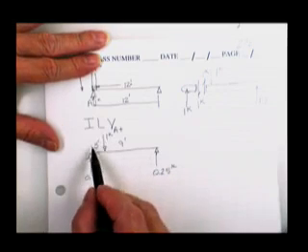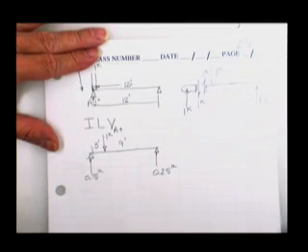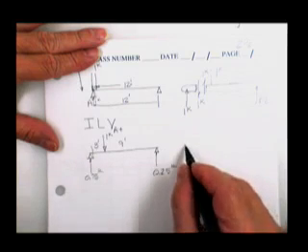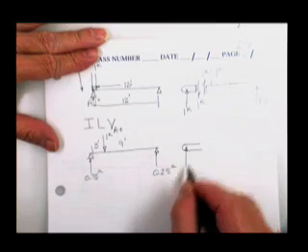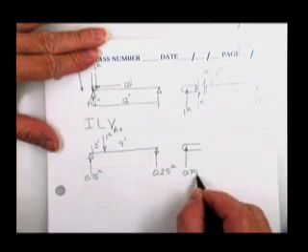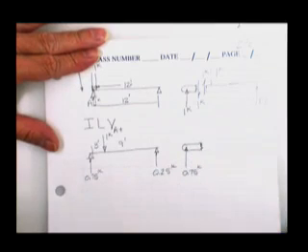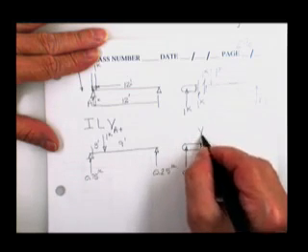And I am going to cut the beam very close to the reaction because that's where you've been asked for the influence. You've been asked for the influence inside the beam in shear, slightly to the right of point A. Here's the free body. Here's the 0.75 reaction. Here's where you cut it. And here is the resulting shear inside the beam.